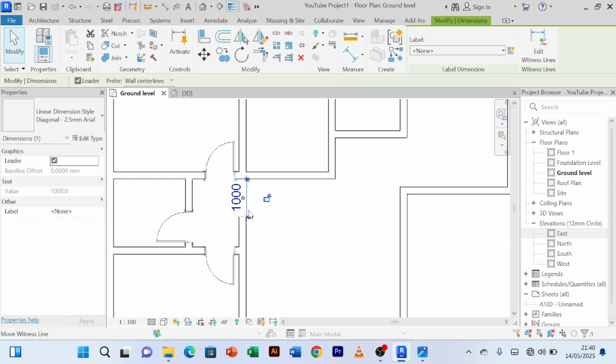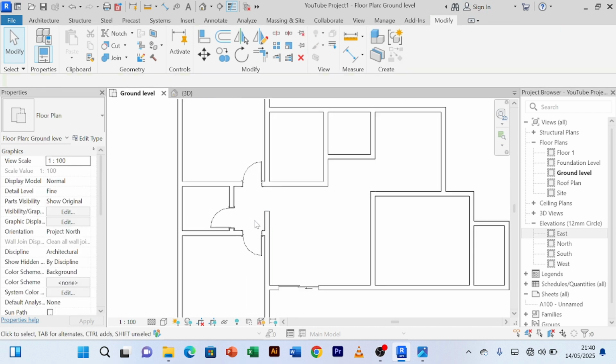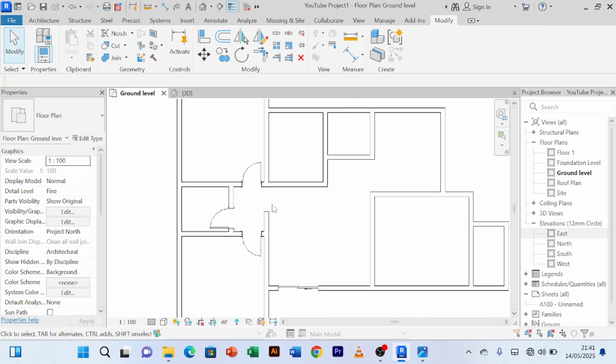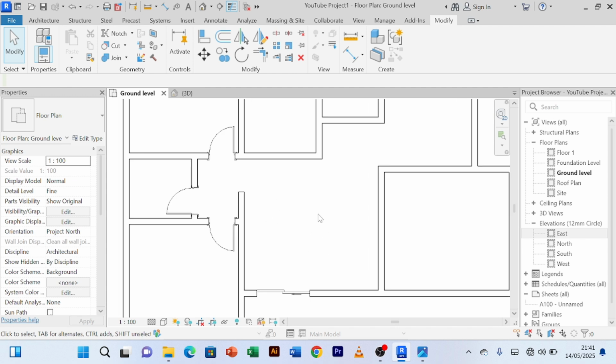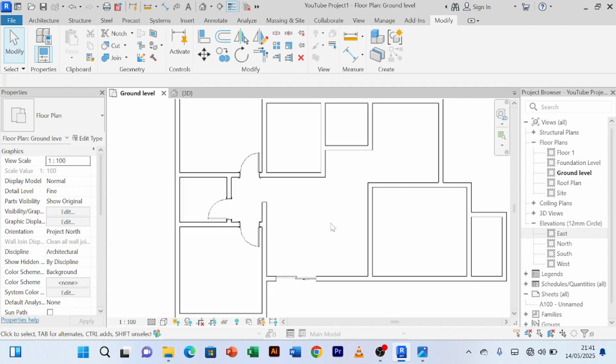So now if someone enters from here, they will not see directly into the washroom, our common washroom. So for you to access the common washroom, you need to come from this side like this. So you make sure every room has some kind of privacy from the public, because this is our lawns or the living area.